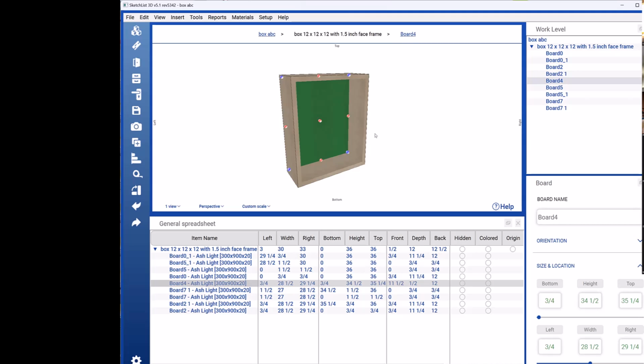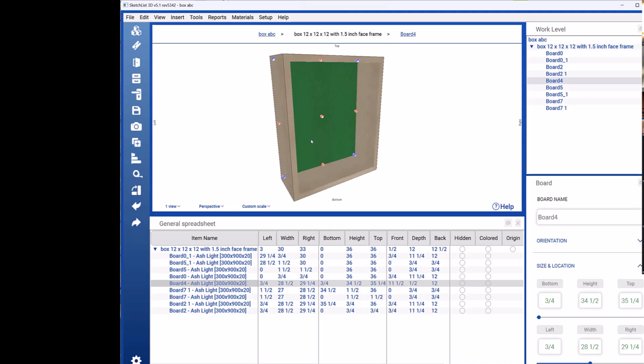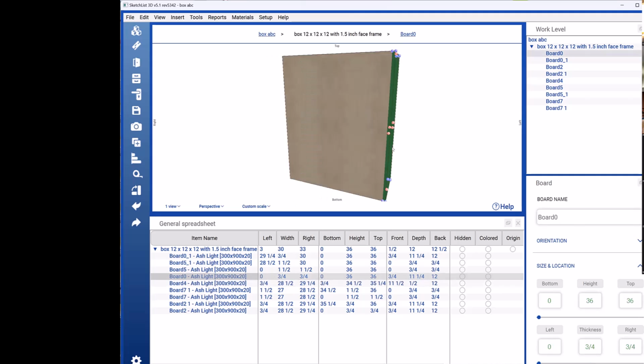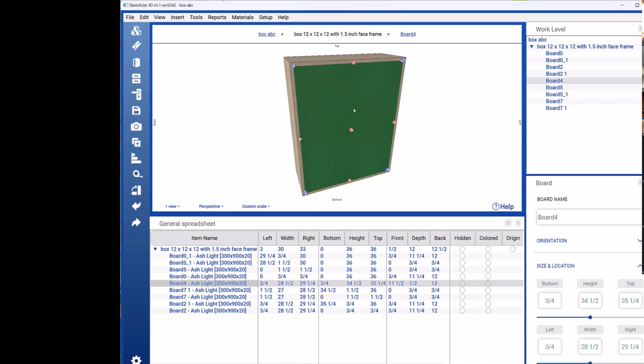So that back panel, let's just take that back panel on your cabinet you have there, right? So typically I will put in a 1/4-inch dado on each one of those boards on the back. If I'm using a 1/4-inch Luan or 1/4-inch board on the back side panel, I'll put a 1/4-inch dado 1/4 inch from the edge, and I'll put it a 1/4 inch deep.